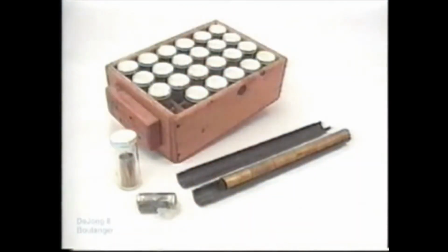After the sampler is withdrawn from the borehole, the engineer disassembles the split spoon and inspects and classifies the material. The sample is then stored, such as in a sealed glass jar, and shipped to the lab for testing. If the split spoon contains two or more distinct soil types, each soil type should be stored separately, or they may get intermixed and subsequently misclassified in the lab.